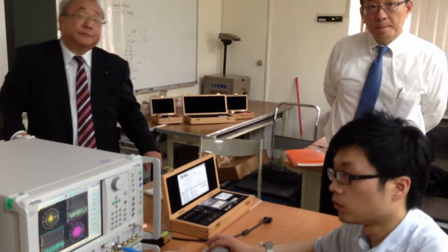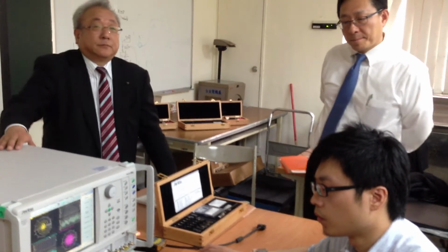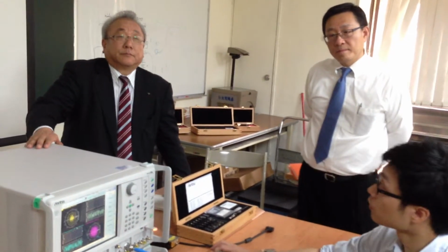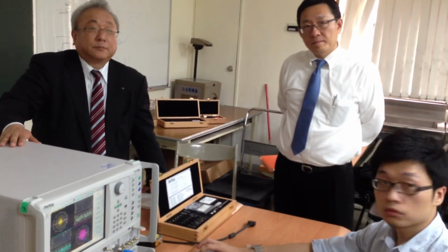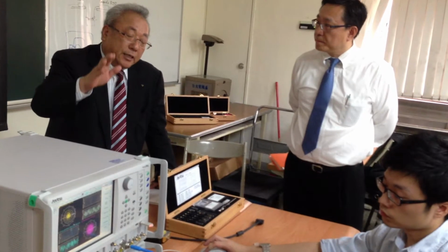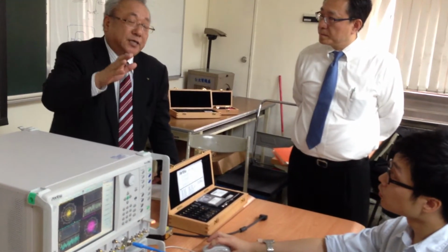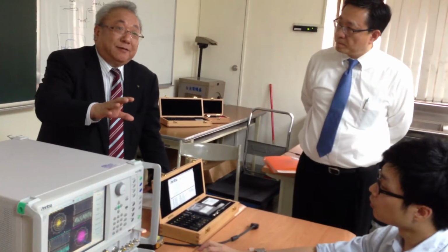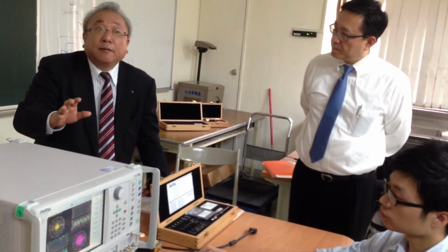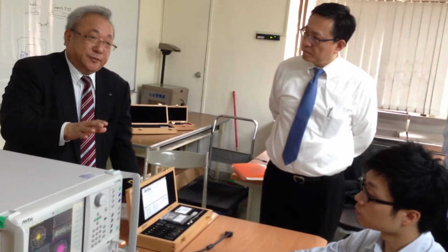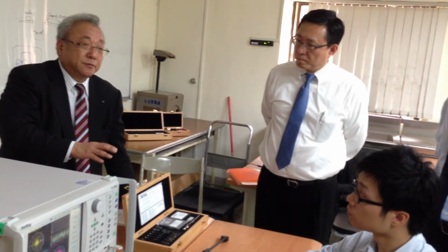So if we measure the noise figure, we only calibrate one time. After this, we can use this data for every measurement. And you have to do the noise calibration. That is a must, because the noise depends on the temperature or something like that. So that is very important. You have to do noise calibration, but the receiver calibration only one time.